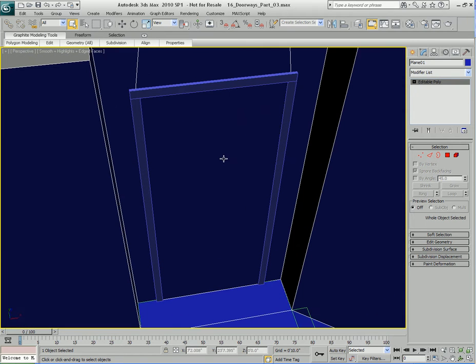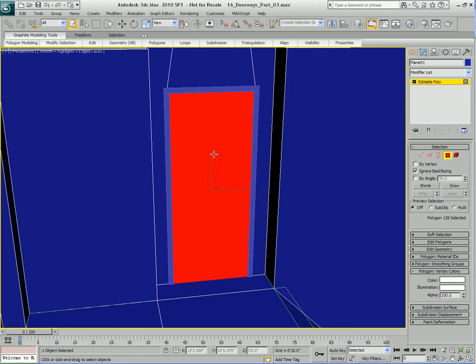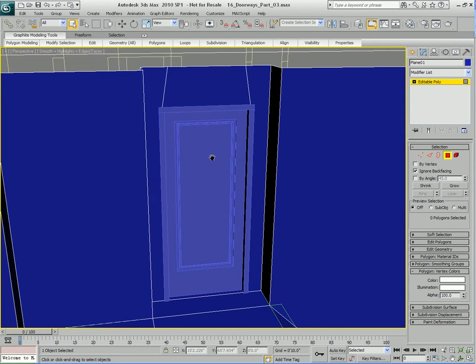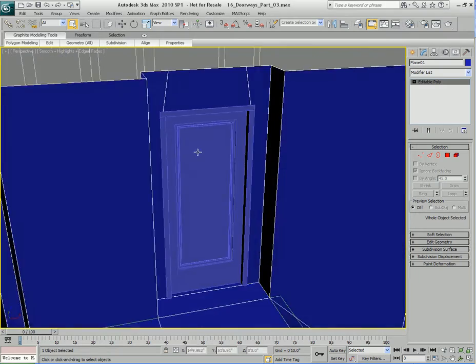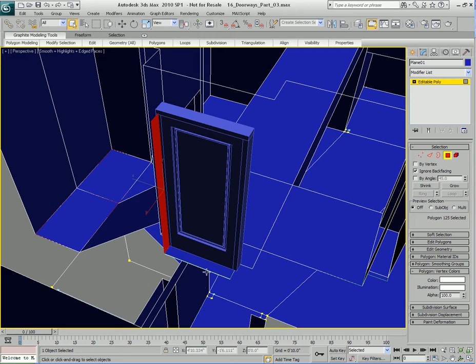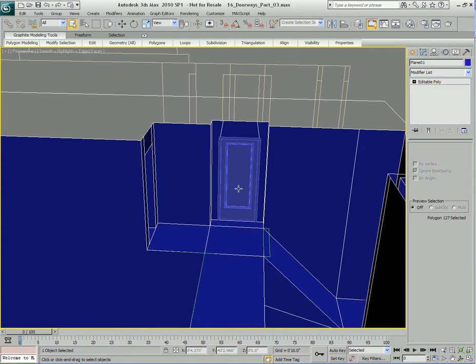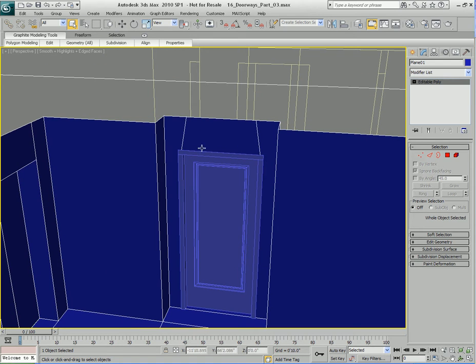So all you would see is this empty door frame just sticking through the wall, and you wouldn't be able to see the actual door, which of course would be a serious problem. So let me delete that polygon that I just created temporarily just to illustrate that. So that's why we needed to make this extrusion into the house geometry for the doorways. Okay, very important. Alright, so that's pretty easy.